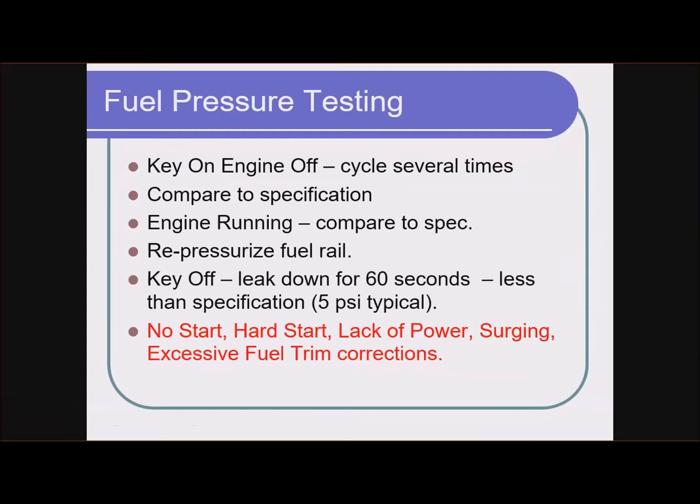So on idle, you might have 30 or 35 psi. Stomp on the accelerator, it might go up to 50. And I'm just pulling these numbers out, so don't go by those. Actually, look up the specs for the vehicle you're working on. So you're probably going to have a key on, engine off spec, and you might possibly have an engine running at idle spec. And those are the two you want to compare.